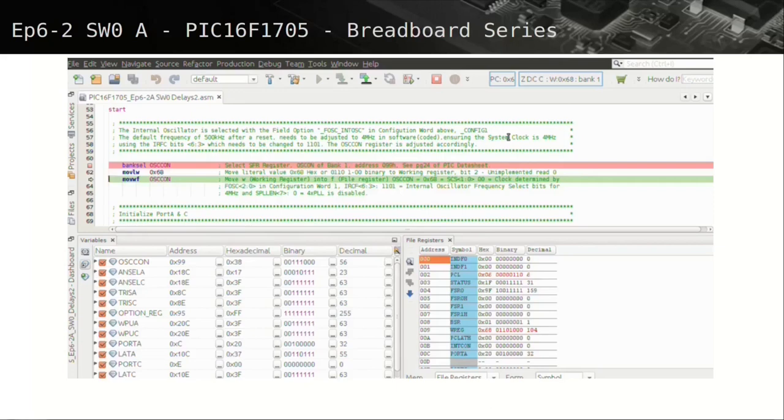Another step into, or F7, executes line 62, which loads the hex value 68 into the working register and moves to the next line of code. The working register now holds the value of hex 68, or 01101000, and the program counter value has incremented to hex 6.